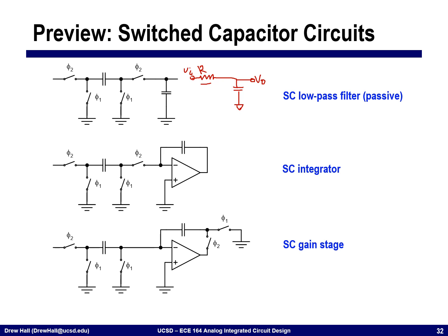We could also build integrators, and so again, normally I would have a resistor coming into my amplifier. Here, I've replaced this structure with a switched capacitor resistor.